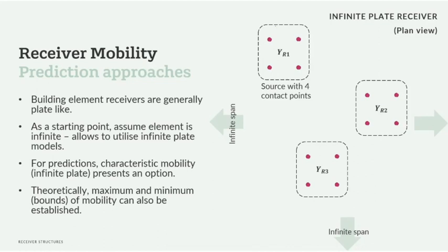As a starting point, we can use those relations to establish a mobility of the plate. And theoretically, relationships have been developed to also establish the maximum and minimum bounds of the mobility for that kind of construction. So you're not only looking at a simplistic behavior, but you can also put a bound on it: what maximum can it go to, and what minimum.